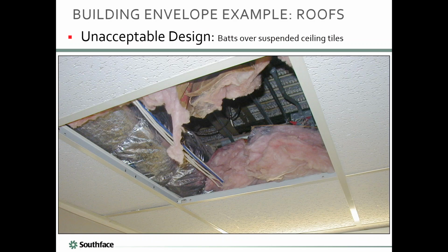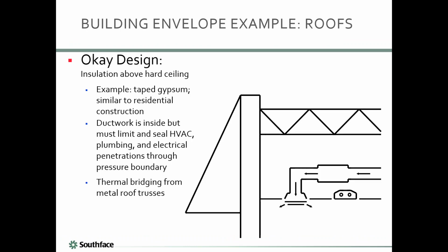It's not continuous insulation coverage. It's certainly not airtight. And it just has all kinds of air quality issues. So don't do this. You can do it for acoustic reasons, but it absolutely won't count. And we don't recommend it. And just appreciate we're going to have to fix a lot of existing buildings.